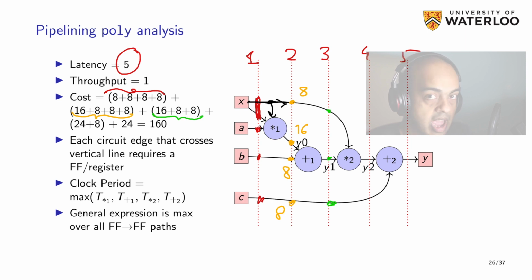And notice that for the add, I didn't have to apply the addition rule of plus 1 bit, because I know that A times X is not going to be the largest possible number. Okay. And then finally, I am going to count these 2 stages, Y2 and Y. I have to also count C2 here. And this will give me the 24 plus 8 signal. So now I know that this is a 16-bit input. This is an 8-bit input. So my result here is going to be 24-bit. And same here as well.